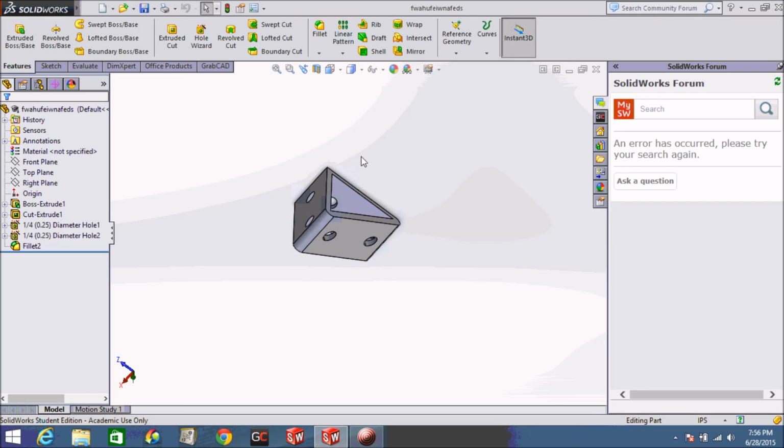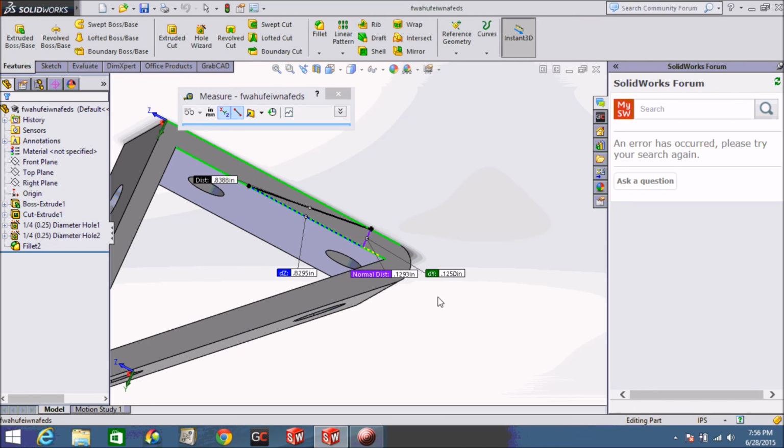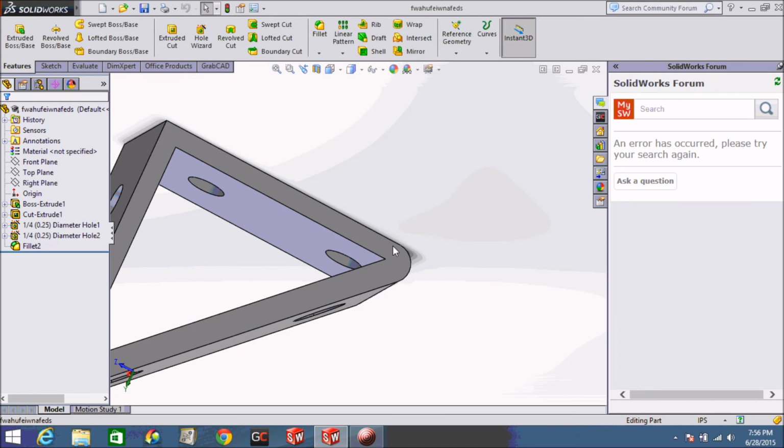Finally, Z, once again, Smart Dimension. X is bound to mate. C is bound to measure. Oh, that's a thing I didn't go over. Press C. It's like Smart Dimension, but it measures things and doesn't actually change dimensions. Yeah, so C is for measure, and this means that when I'm working in the assembly context, I have my basic functions. Once again, I have Smart Dimension on my pinky at all times, so this has allowed me to optimize my workflow a lot, and I'm trying to get these to become the team hotkeys.